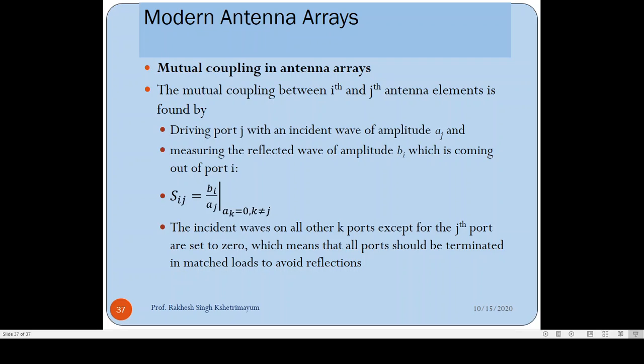So you'll realize that from the conventional array you won't be able to fit 2 antenna elements on your mobile phone. You can do the calculations and you can see. The size of the mobile phone is too small to fit a conventional antenna array with lambda by 2 spacing between the antenna elements.